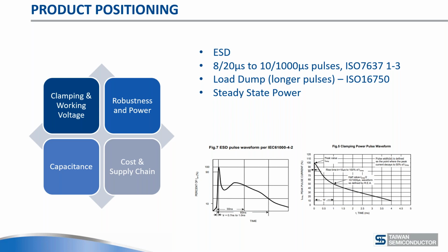A lot of TVS diodes are used in a steady state situation. Steady state means, let's say, a clamp circuit in a flyback transformer where you're protecting the 600 volt MOSFETs, and you need something that has a duty cycle of 1 or 2% to make sure that the 600 volts, or whatever process voltage, is not exceeded. This has steady state power dissipation. There are also other clamps on MOSFETs, for example between drain and source, gate and drain, and other clamp circuits all over in the business, including freewheeling. In that case, the defining factors are going to be your package and your PCB layout.